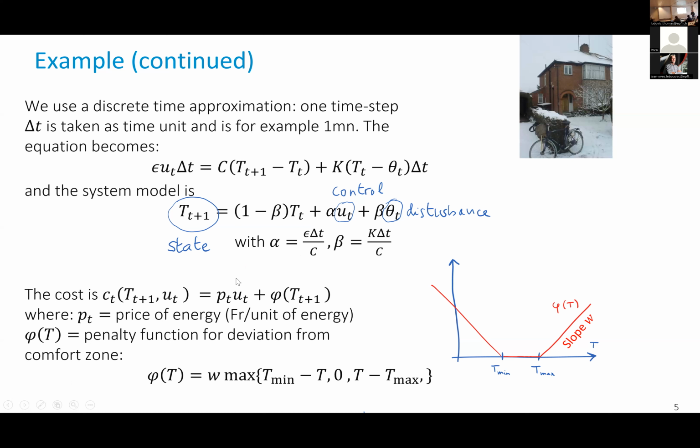Very often when we do model predictive control, we will have large linear programs to solve. And if we put hard constraints, they may be unsolvable, or solving them with a lot of constraints may make the problem very difficult. So instead of that, we often put what is called a soft constraint in this form, which is justified a posteriori by the fact that the program will be easier to solve here. It's also justifiable in this case because this is really a soft constraint. If we vary a little bit here, if we go a bit below here, there is no big damage done to the system.